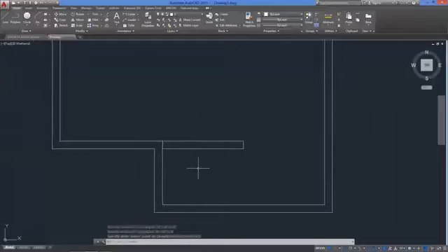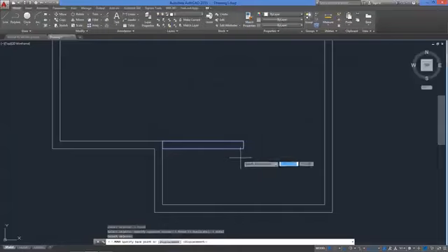Since the final position of the wall is over here, we will use command move to put it in its final place. So we go to modify tab again and click on move. The first prompt is select objects. Notice down here that it tells you the amount of objects you have selected. Now, when you're done selecting them, just hit enter, and the following requests specify base point or.